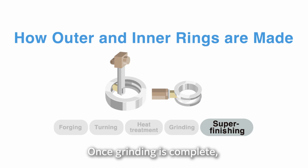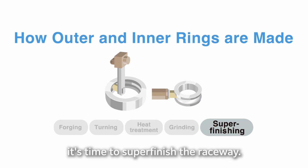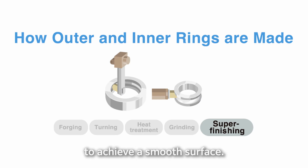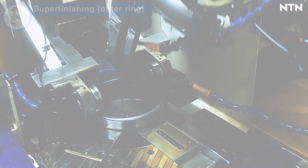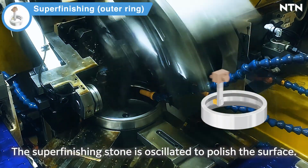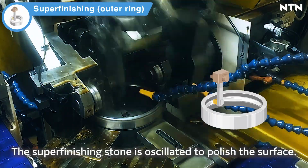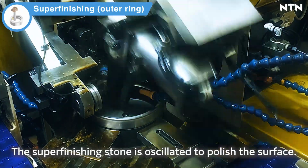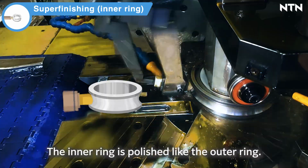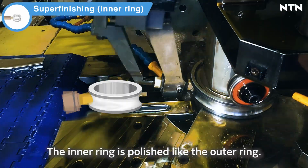Once grinding is complete, it's time to superfinish the raceway. Raceways are polished with a superfinishing stone to achieve a smooth surface. First, the outer ring. The superfinishing stone is oscillated to polish the surface. Next, the inner ring. The inner ring is polished like the outer ring.